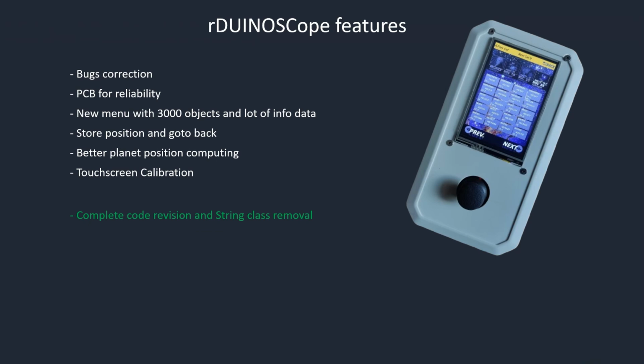The Arduino DUE has a lot of memory and we might think that would not be a problem using this class, but there were actually many variables using this class in the code and there were bugs caused by this phenomenon. We were having particular problems with memory corruption when storing option information on a memory card, so I preferred to remove everything and replace it with char arrays to avoid potential bugs.